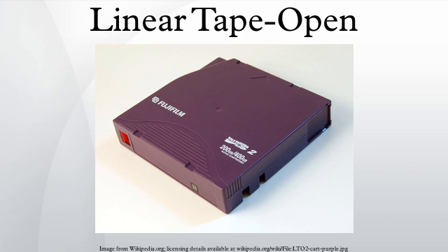A common reason for a cartridge failing to load into a drive is the misplacement of the leader pin as a result of the cartridge having been dropped. The plastic slot where the pin is normally held is deformed by the drop and the leader pin is no longer in the position that the drive expects it to be. Older single-reel tape technologies use different means to load tape onto a take-up reel.